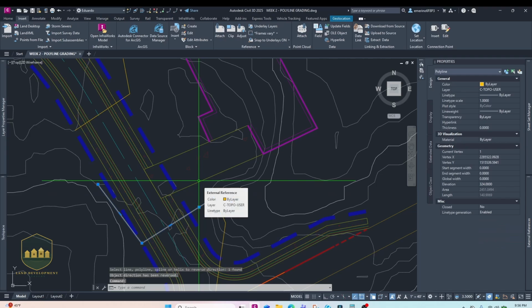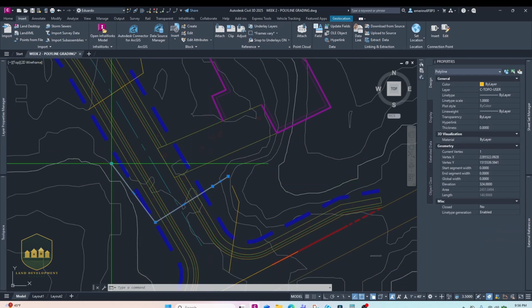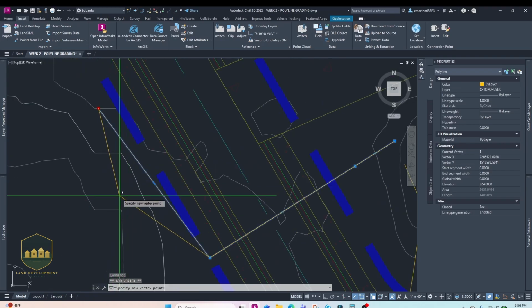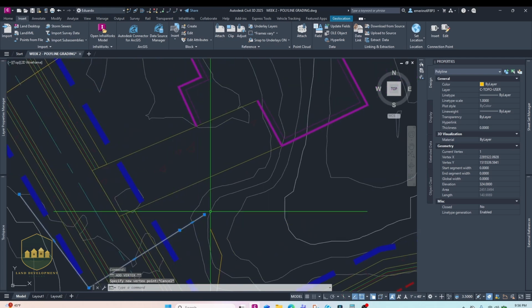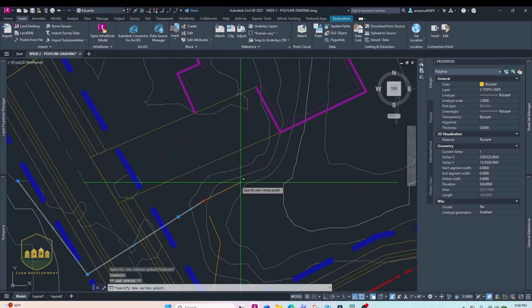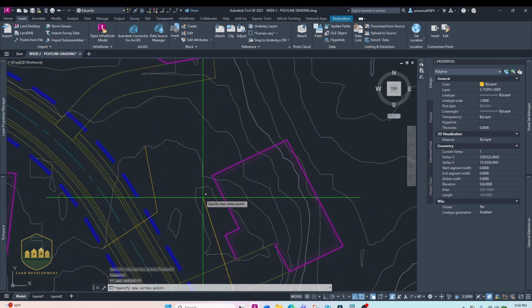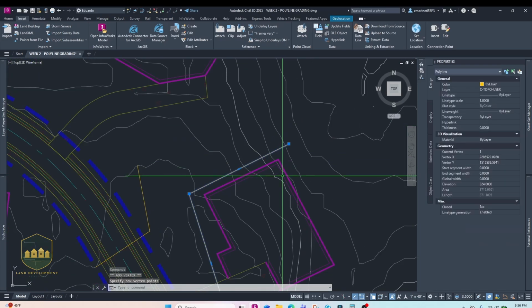I wanted to add a vertex, and when I press add, I can do it here by pressing A, it wants to put a vertex in between these two vertices. But if I do reverse, if I press A on this side now it just spits it out to the other end. And it's a lot easier to control those polylines. And I know it's going to wrap around like this.